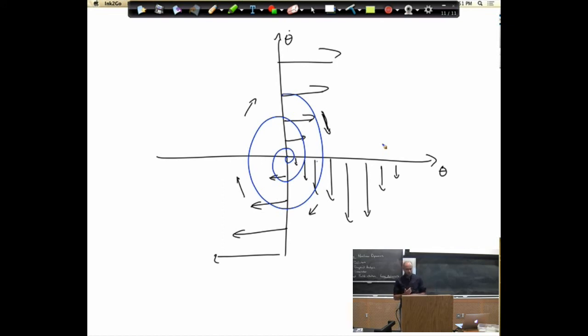Now here's a really important point. I wrote my equations here. We said that x dot is really just x2, let's say, and then 1 over ml squared, I could almost leave that out, that's not the important thing, u minus b x2 minus mgl sine x1. So that's what makes up these vectors. What happens now as I add u? What can u do to my vectors?